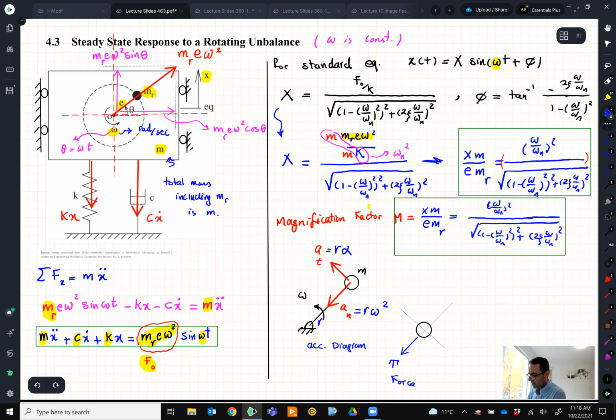So looking at this diagram, I can write down Newton's law. Sum of the force must be equal to m a in the direction of n. So in the direction of n, I have one T, and I have m multiplied by a_n, which is r omega squared. Okay, so far, do you agree? Yes. So this is the standard way that we do these things.